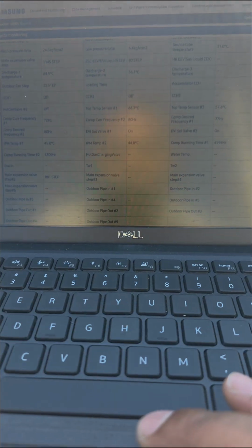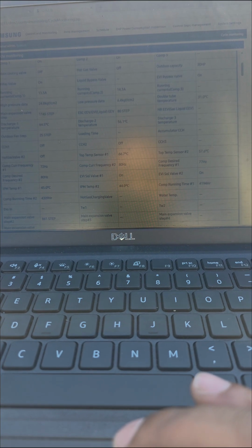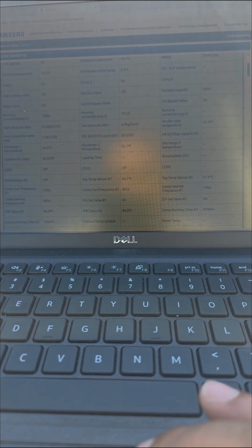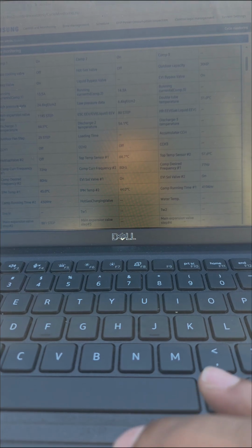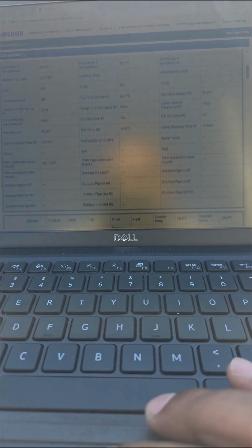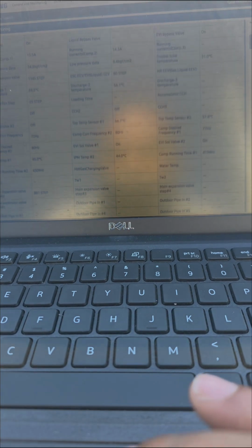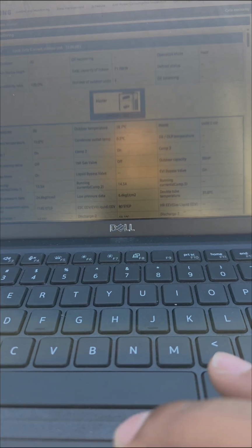I think I'll set up to run the service check on it. Discharge, auto fan, hot gas. I'm not seeing the suction 1 and 2 temps. So yeah, let's plug the service check in and utilize that.